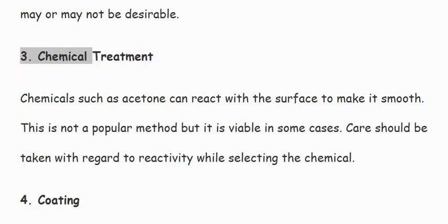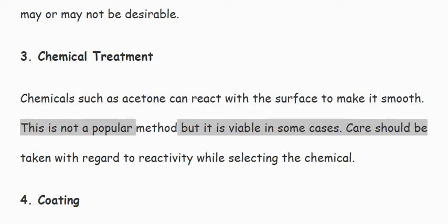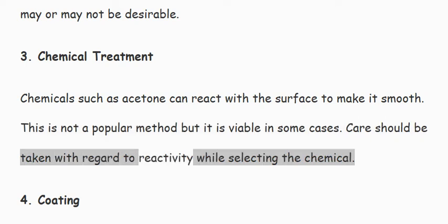3. Chemical treatment. Chemicals such as acetone can react with the surface to make it smooth. This is not a popular method, but it is viable in some cases. Care should be taken with regard to reactivity while selecting the chemical.